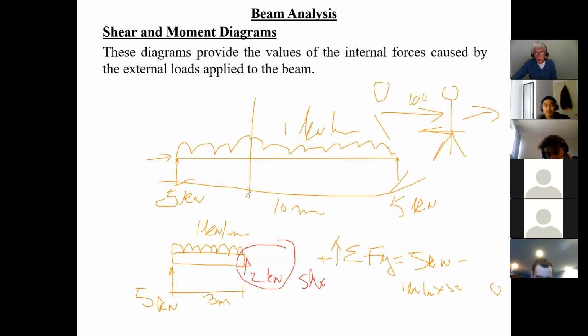So what the shear force diagram does is tell you all the upward or downward forces to keep everything in equilibrium. Those are the internal forces. Anywhere along this beam, when I want to know what's happening inside the beam, I have so much coming down, so how much do I need to push up?